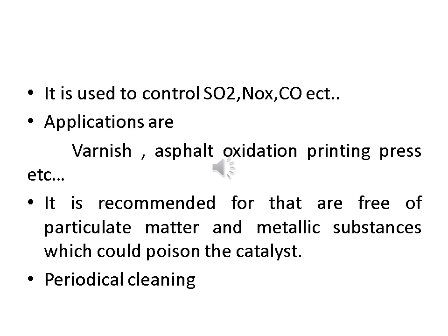And then this catalyst bed is cleaned periodically, that means quarterly or annually, by scrubbing with water or sometimes with acid, or by heating with high temperature, etc.